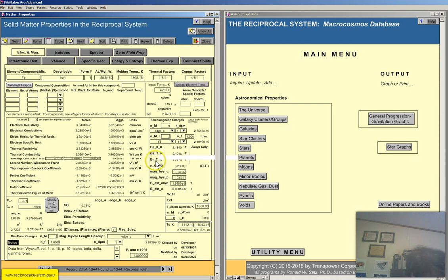And then here's that at remanence, internal magnetic flux density, temperature, T. This is the average relative permeability of the ferromagnet in the second quadrant of the hysteresis curve. That's at room temperature, incidentally. And here are the parameters for the hysteresis curve.